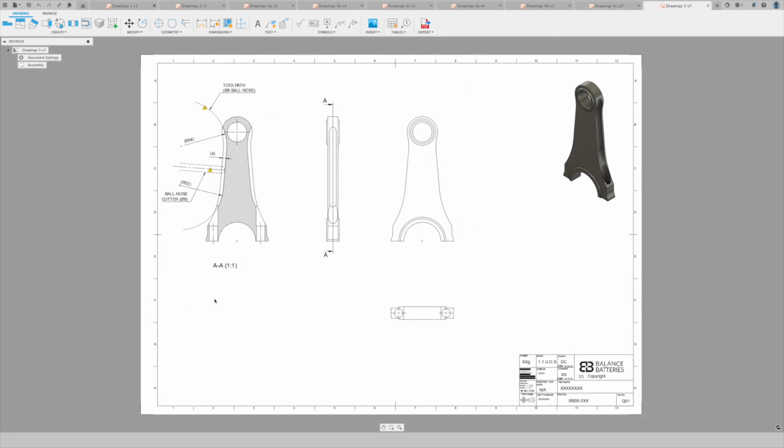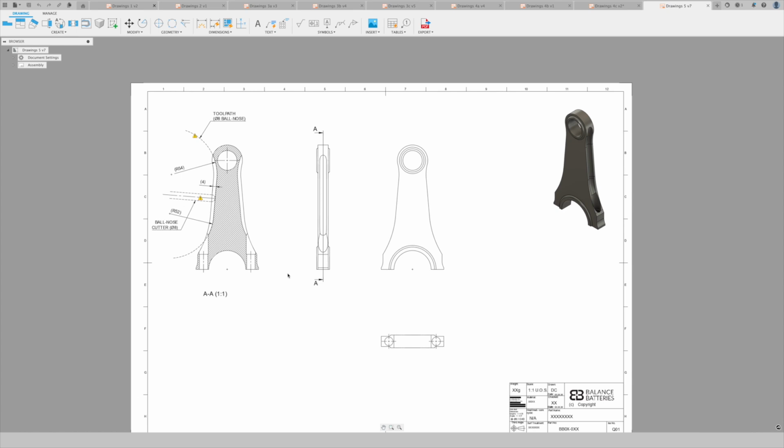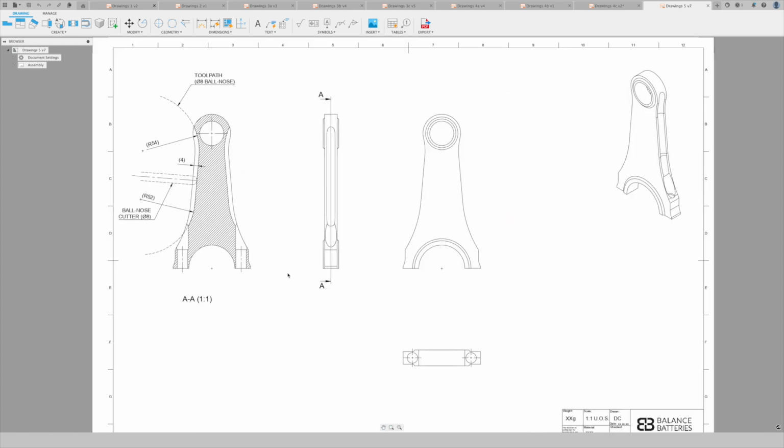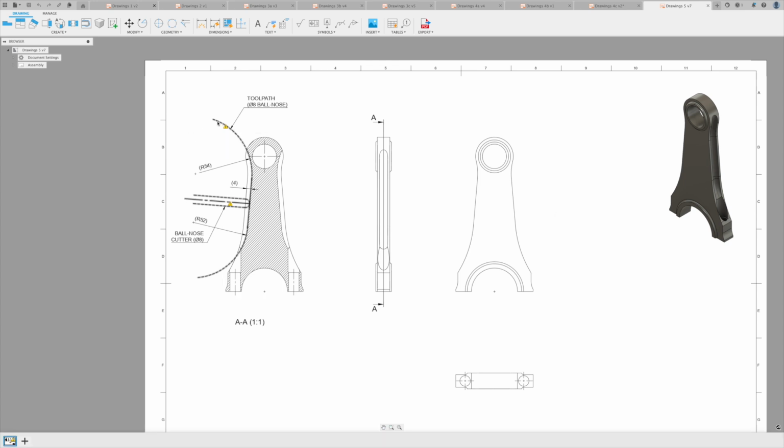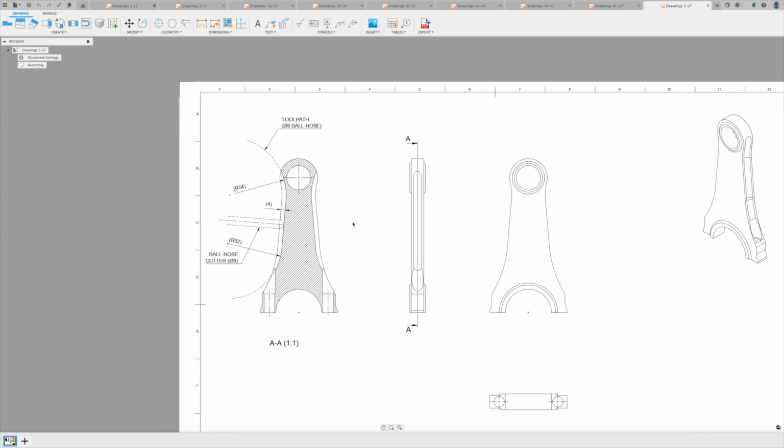The last point I want to make is shown in this drawing here, which is the top part of a connecting rod assembly. There is a lightening pocket in the side of the part. In this case, we've specified the tool type and dimensions as well as the tool path, which means that the tool path can be programmed offline directly on the machine, rather than by using specialist CAM software, again saving time and cost, whilst achieving the result that you wanted.